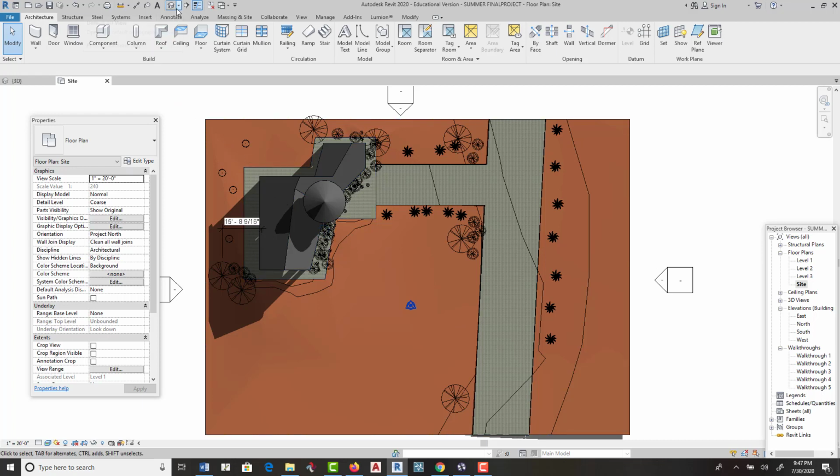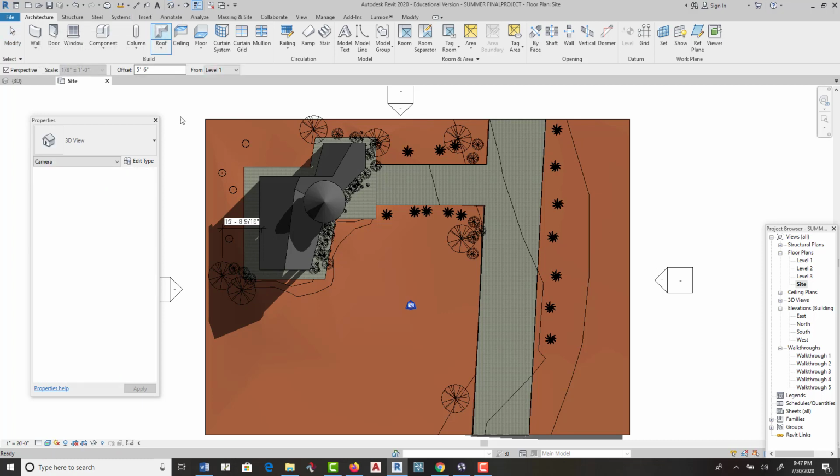So let's go to annotate with the little doghouse. And let's go to camera. Now, if you start your camera, you're going to be in perspective because that little check over there is perspective. So you uncheck perspective, that's coming up next.